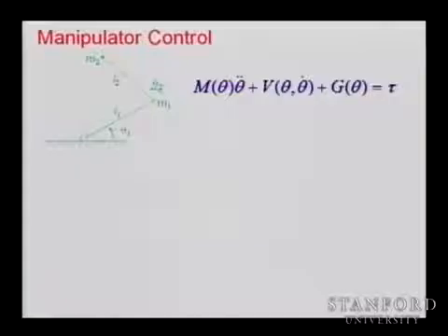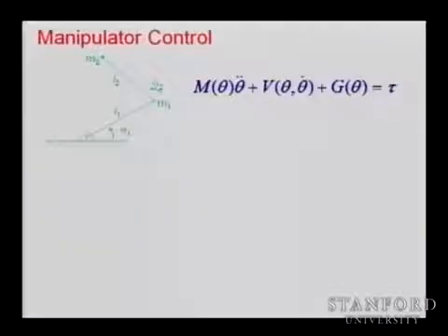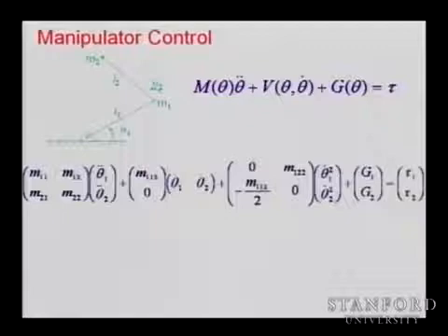If we add 1 more degree of freedom, that is, if we have a robot with some dynamic coupling, we are going to see that the performance of a PID controller is not going to be satisfactory, especially if we are tracking a trajectory. So this equation of motion you're familiar with, I'm going to rewrite it in 2 equations.